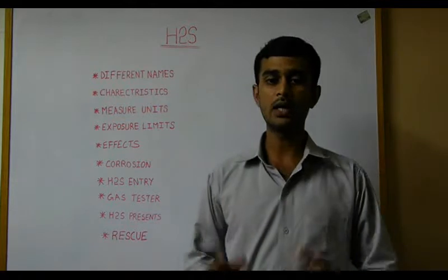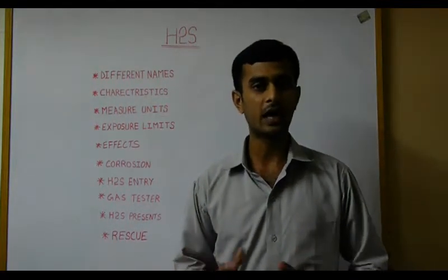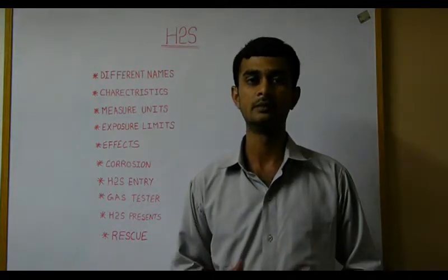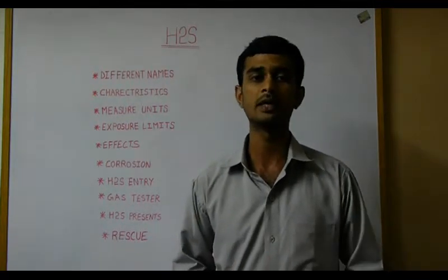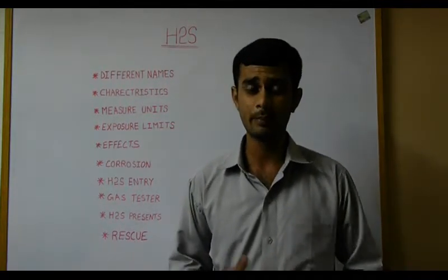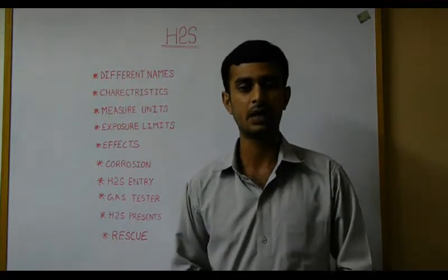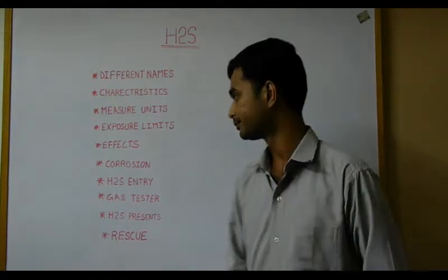H2S entry. While entering into the H2S zones, it is mandatory that you have a hydrogen sulphide work permit or H2S work permit, along with your gas testing device which is working properly, and your breathing apparatus which is self-contained type or an emergency life-saving type. Coverall, helmet, safety shoes are also necessary.